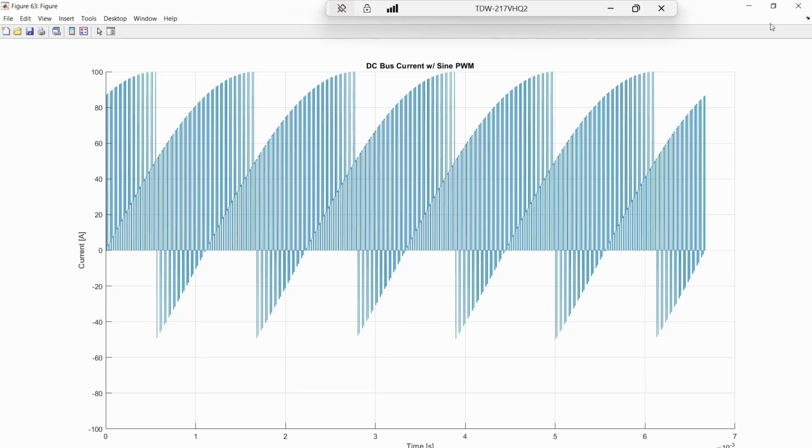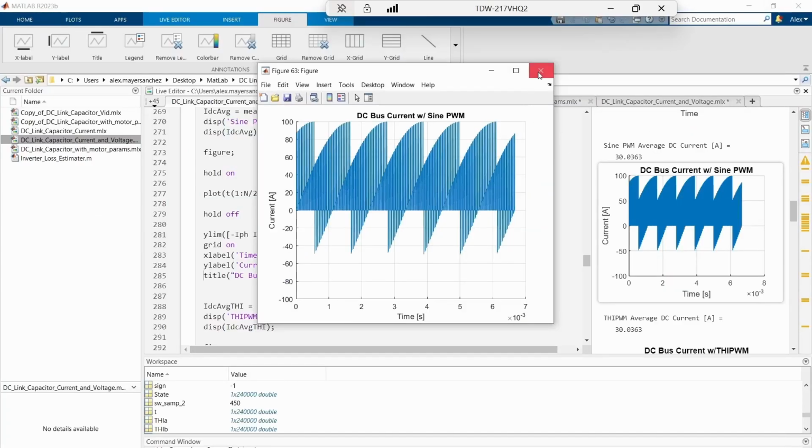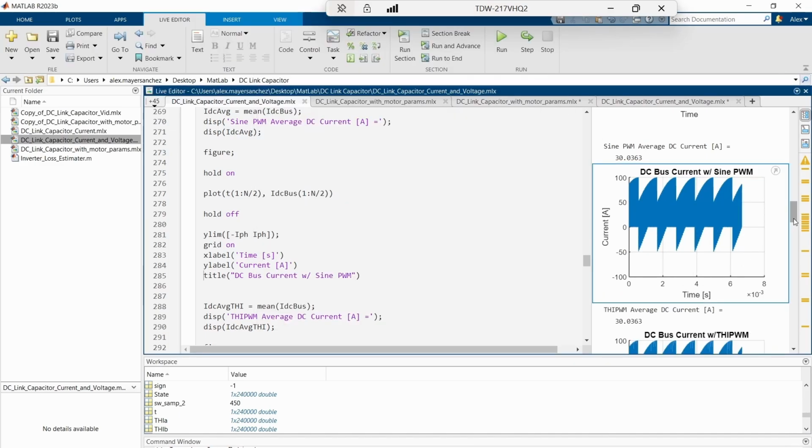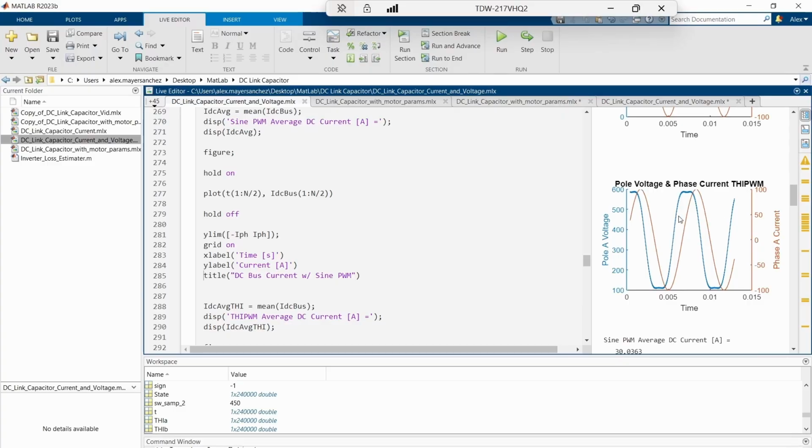And that's because, since the current is lagging the voltage now, when you multiply the instantaneous power of this equation, the power actually goes negative as well.